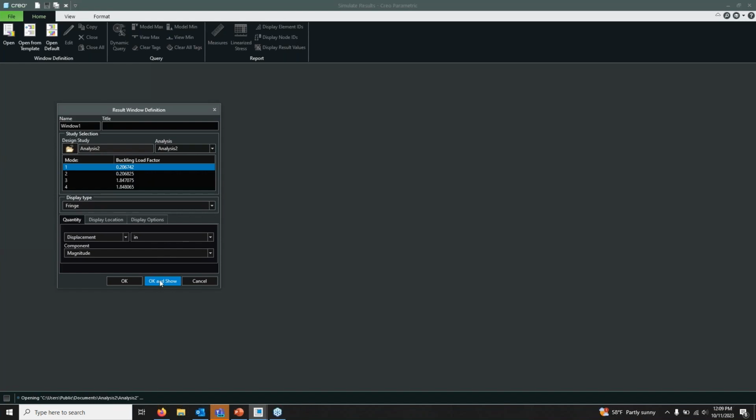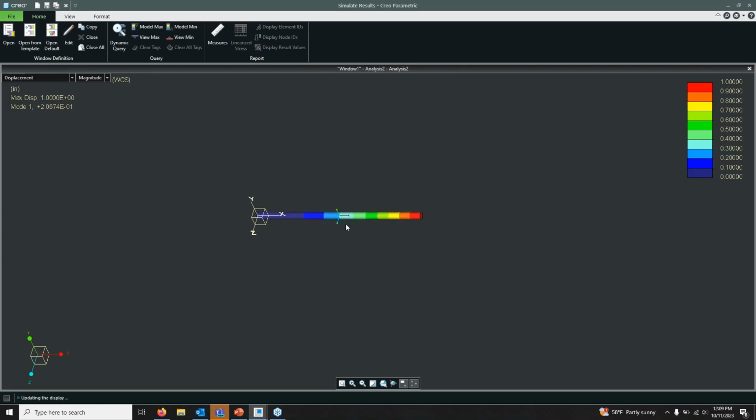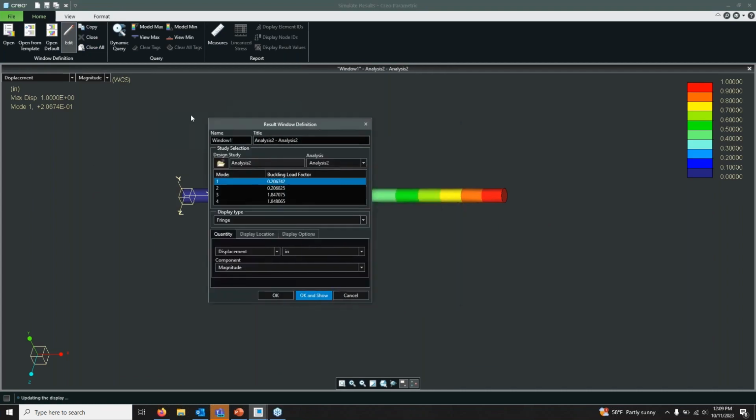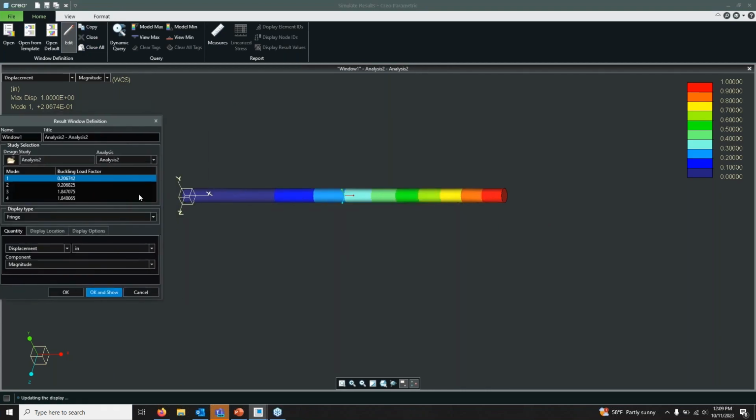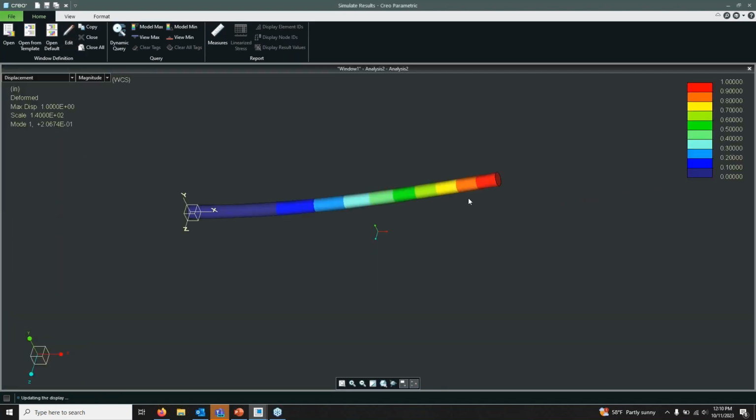So just for reference, this thing would not fail in the traditional sense. In terms of tensile yields, this thing would not fail, but it is going to basically fail 5 times over due to buckling. That emphasizes that we are always going to want to test buckling in any compressive axial load case. It's always going to be a good idea to check this.